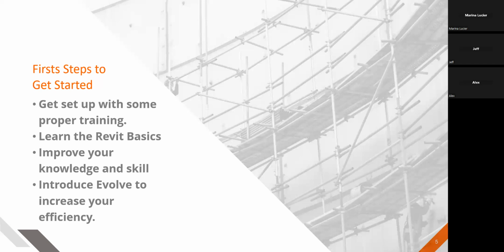But you could essentially put in a bunch of section lines and views, and put all those views on a sheet to create a spool drawing. Would not recommend doing that. I'd recommend going either the scope box or the assembly route for that. You're going to make your Revit workflow a lot cleaner that way.